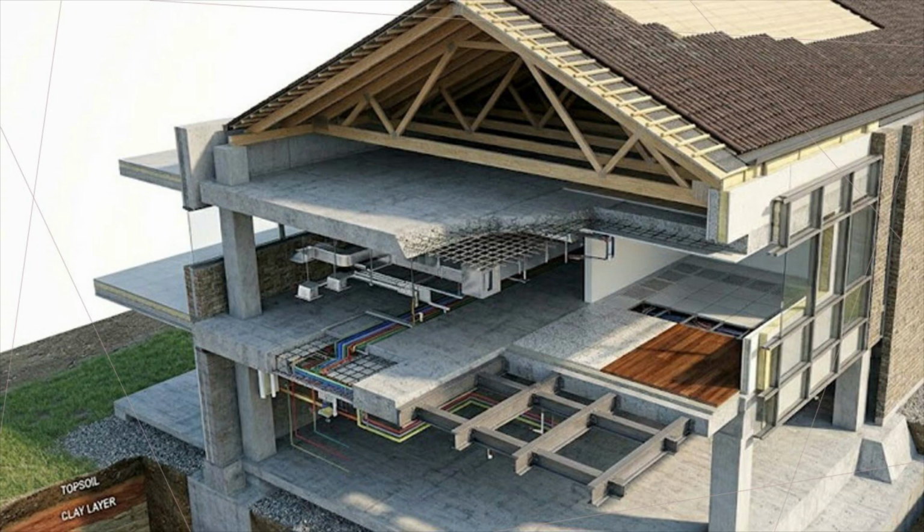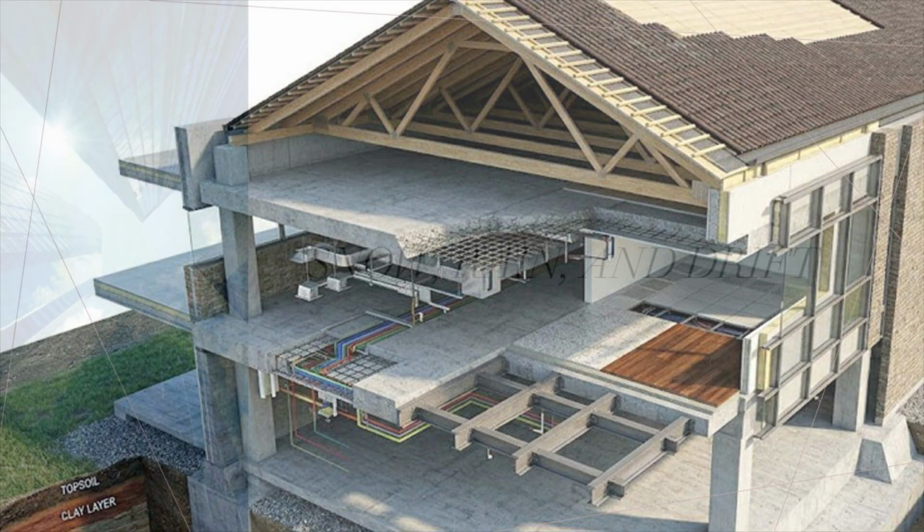Dead load includes the self weight of the structure along with any permanent architectural and MEP components. Live load accounts for occupants, furniture, and movable items, and may be reduced depending on the number of floors and tributary area. Roof live load is typically 20 psf, but can be reduced down to 12 psf for larger areas.